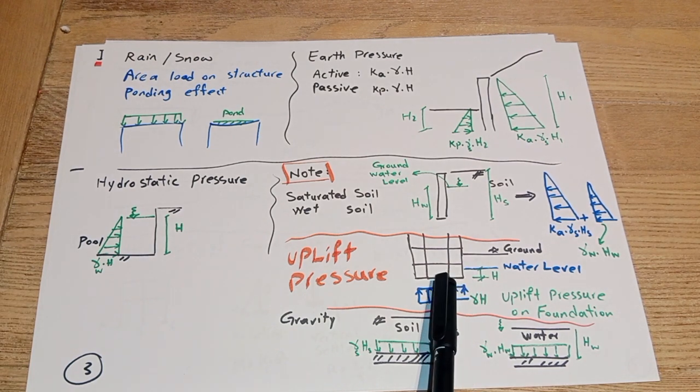In this case, we may need increased weight of the structure, increased weight of the foundation, or sometimes screw piles to take the tension loads from uplift pressure.